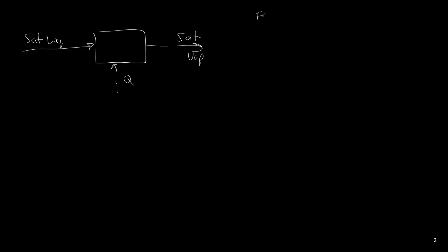So if we go to our energy balance, for an open and steady system, we have in is equal to out. Effectively, all we're doing is figuring out how many streams are providing energy into the system, which is our boiler right here, and then subtracting out all the streams that leave. For the way that I've drawn this particular process, we have enthalpy entering in this stream right here, and we have an out stream there.